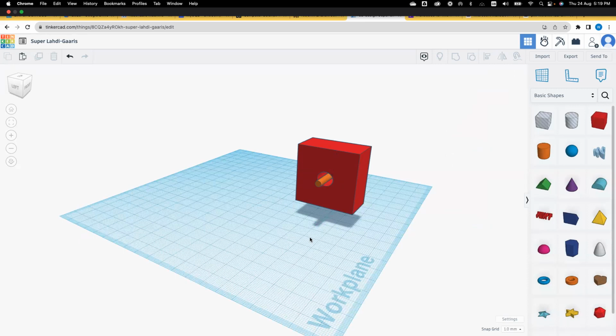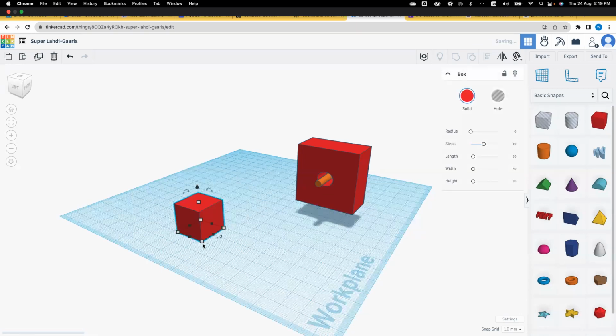So I showed you the properties of the boxes, how to raise, how to create a hole, how to duplicate, how to align, and now it's time to see how I can duplicate objects. And believe me, all you need are those simple manipulations, and to keep the creativity of the students in order to imagine objects, solutions for what you are giving. So I will take, let's say, another box. I will make it like 5 by 5.